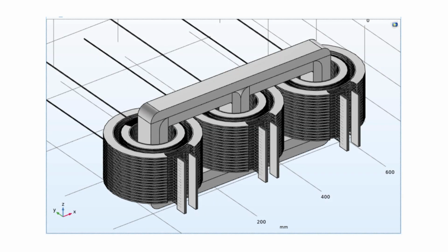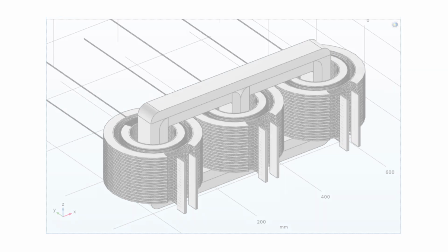We chose a core-type transformer with cylindrical windings because this setup best balances the leakage inductance with the current conduction losses. The final design has an efficiency of 98% and a mass below 50 kilograms, making it ideal for scalable SST systems. With the prototype realized, the next step was then to verify the insulation integrity under the operational stresses, and we started with partial discharge.